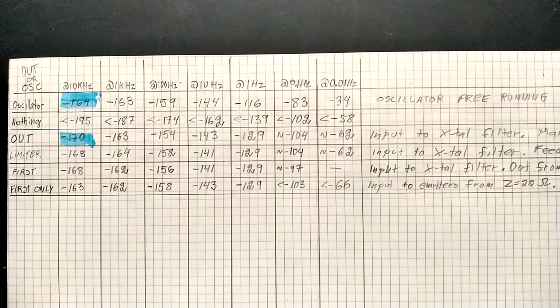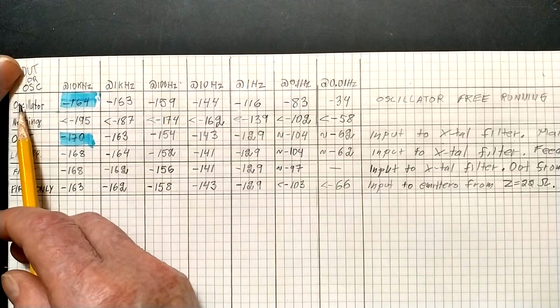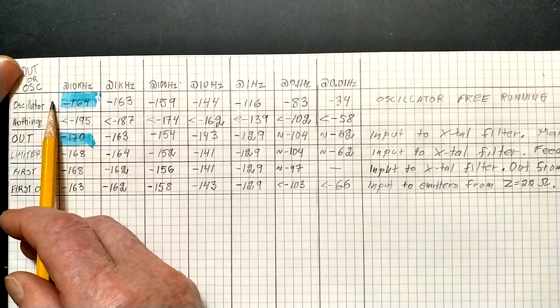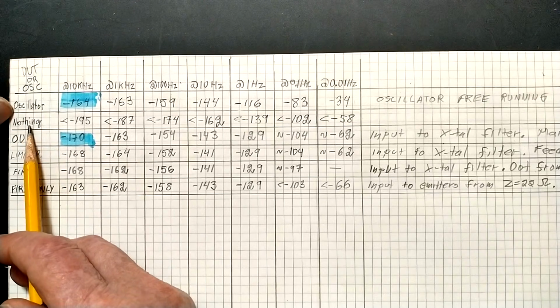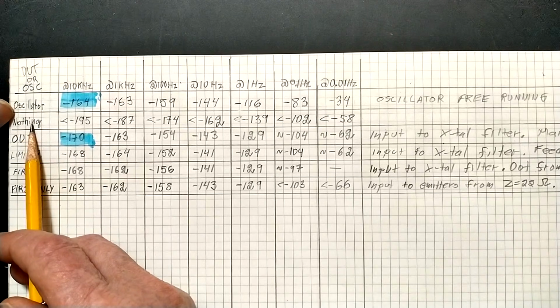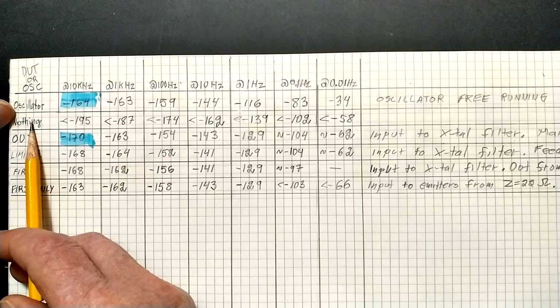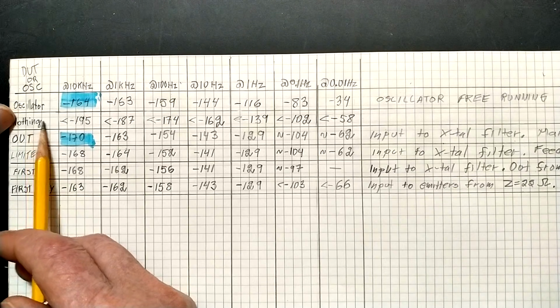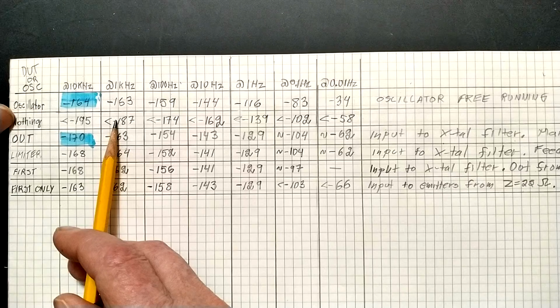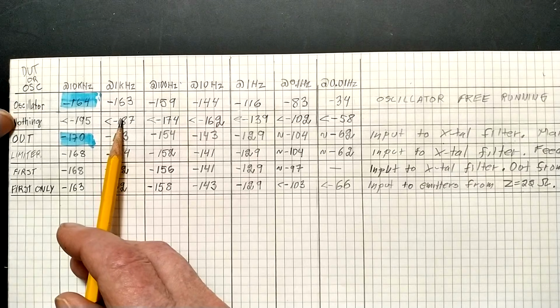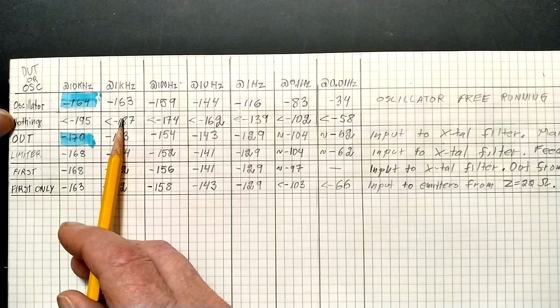I have made a couple of phase noise measurements now. The top line is the oscillator measurement you have just seen, and the next line is running the unit as the device under test in the interferometric setup with the PN2060. And the first row here is with nothing, meaning a BNC to BNC female adapter. And that's the limit of my test system then.